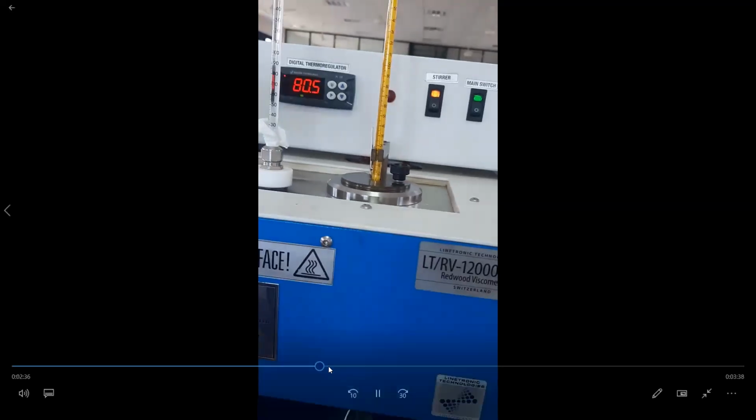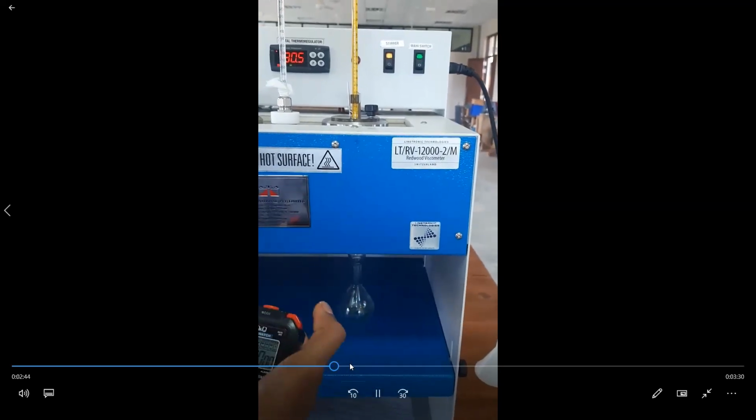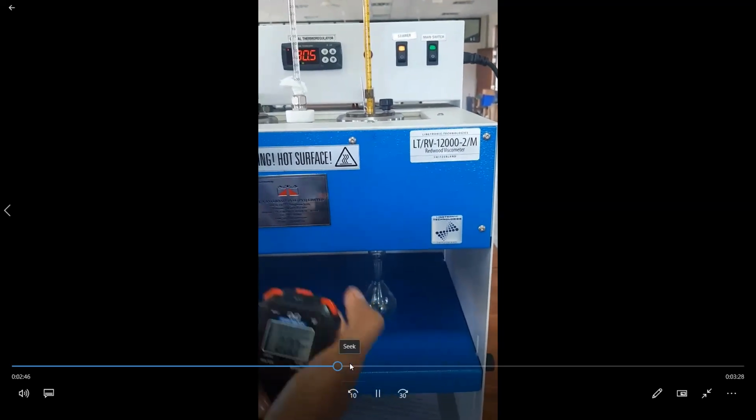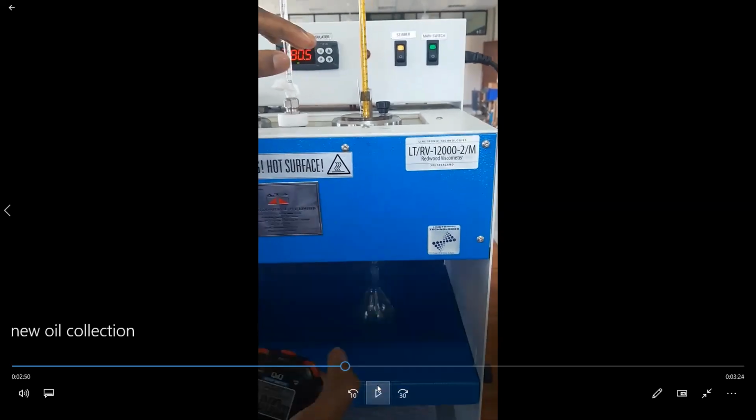So here we are going to find out the time to collect 50 milliliters of oil sample at this temperature. The data we need is the time, how many seconds it took to collect the 50 milliliters through that orifice. That is what we need.